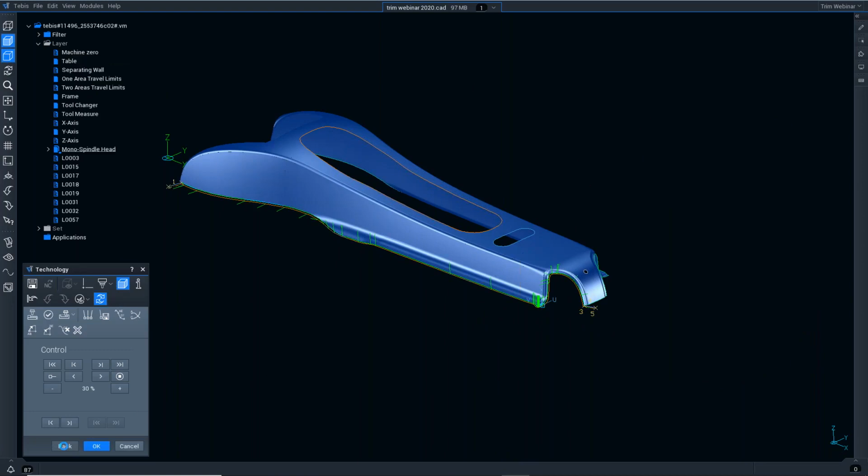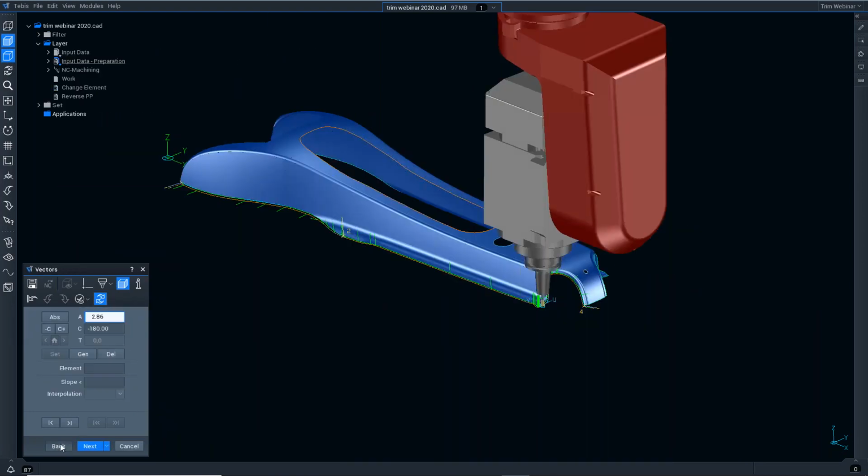Okay, so next will be if we were to have a drawing change. So if we have a change in data, or we have some extra data that's being handed to us, which in this example is this new curve here, rather than go through the process of redrawing our curves, reconnecting our curves and redoing surface data, what we can do is we can just add this in and Tebis will interactively take account of the new path and adjust accordingly.